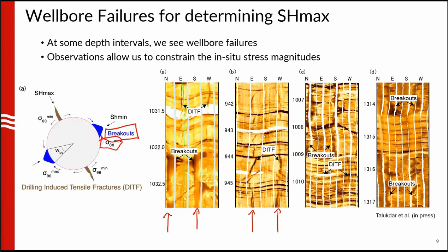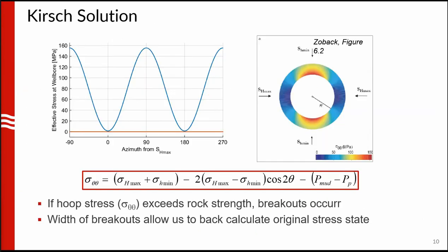So what we're saying is that with the azimuth theta, the stress magnitude changes in this sinusoidal pattern. And so you can see that in some regions you have high stress and low stress, and this is because of the stress concentration you get because you take out the rock that used to fill the borehole. But anyways, because of this, you get this stress variation.